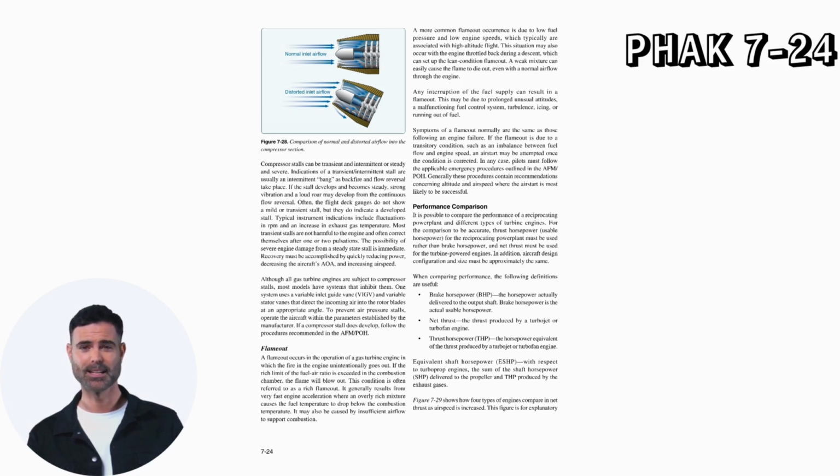Often, the flight deck gauges do not show a mild or transient stall, but they do indicate a developed stall. Typical instrument indications include fluctuations in RPM and an increase in exhaust gas temperature. Most transient stalls are not harmful to the engine and often correct themselves after 1 or 2 pulsations. The possibility of severe engine damage from a steady-state stall is immediate. Recovery must be accomplished by quickly reducing power, decreasing the aircraft's AOA, and increasing airspeed.